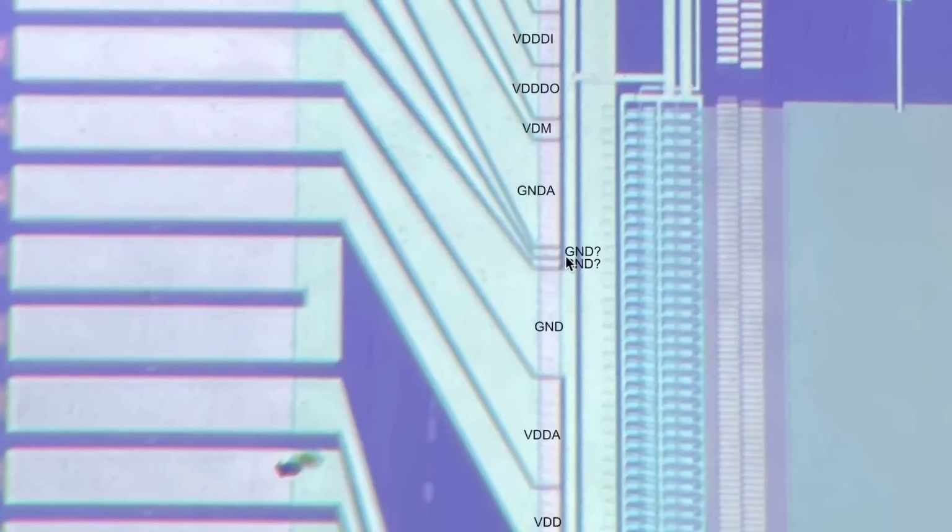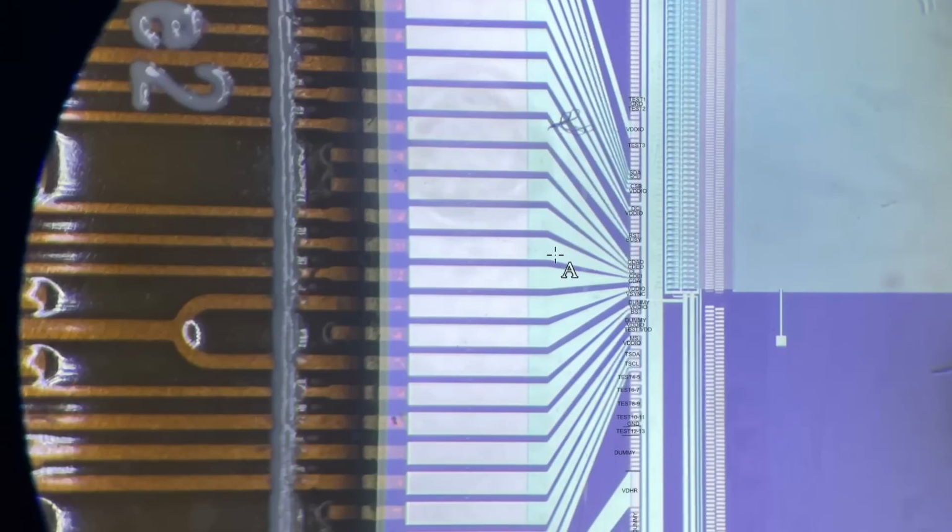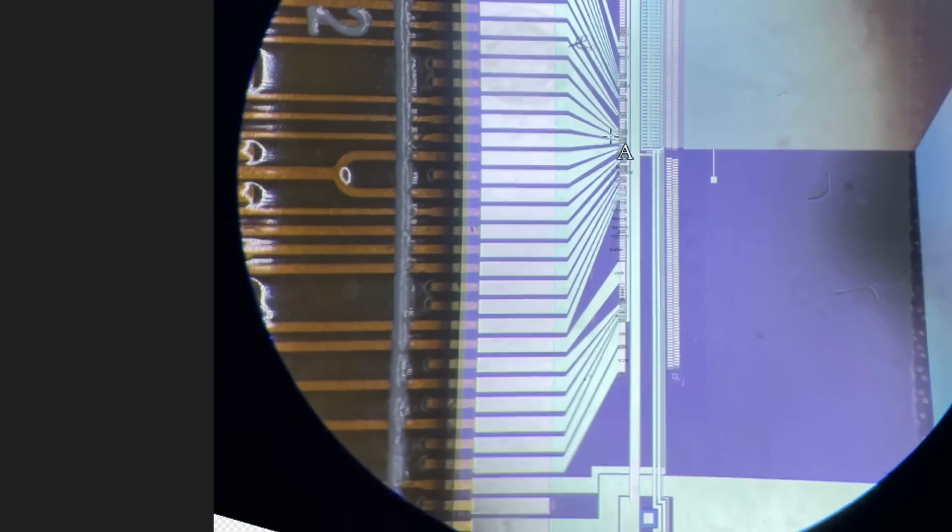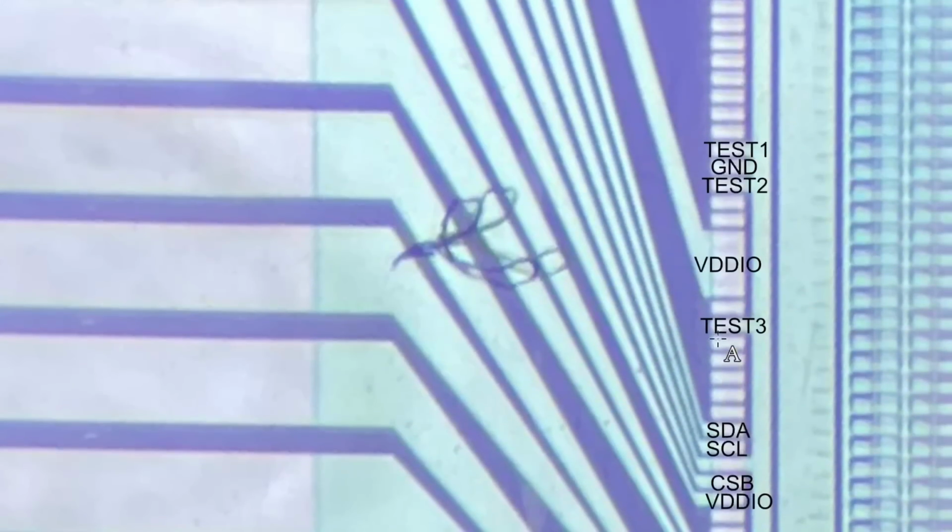I do see some discrepancies here. These 2 pins are marked as ground, but on this actual screen, these 2 are fanned out, not shorted to the rest of the ground. I will leave this as a question to be answered soon. I also took another photo for the lower edge. Similarly, you can derive all these connections. This part contains all the important signals that I will eventually trace through to the ribbon connector.